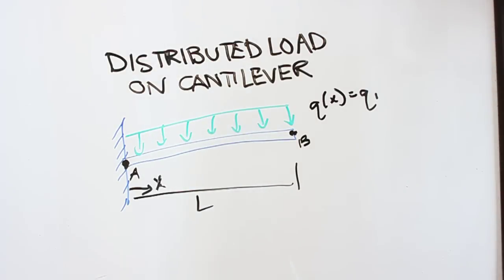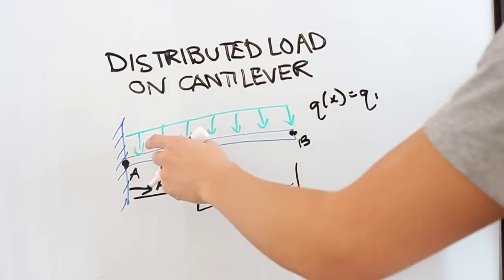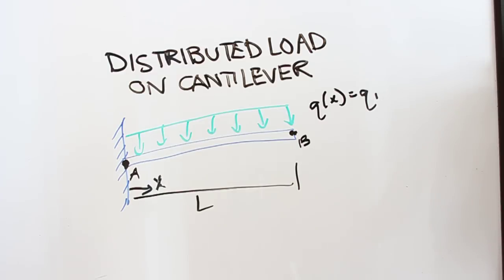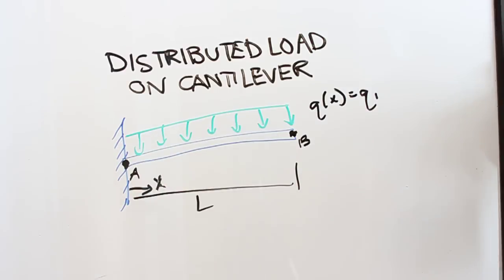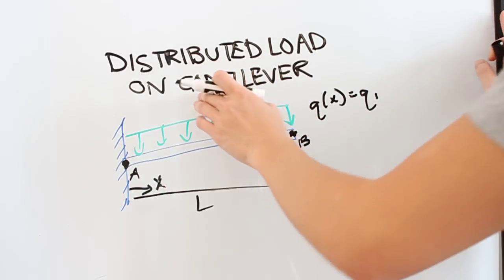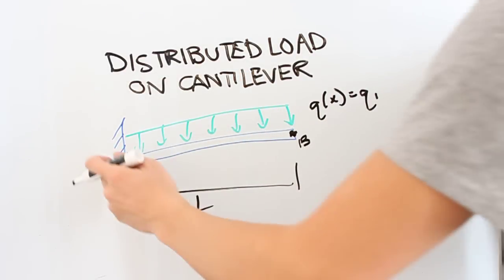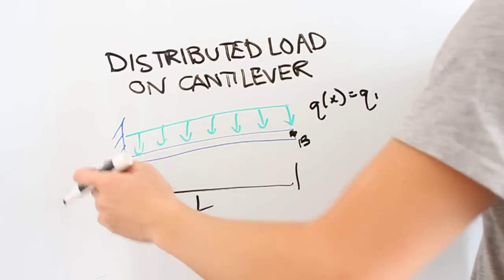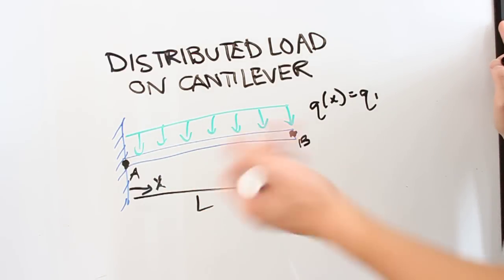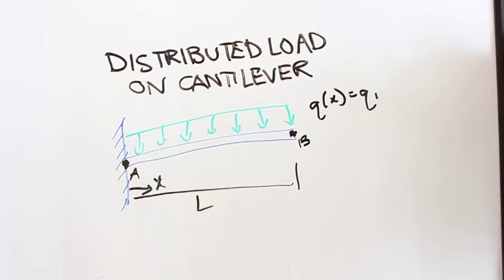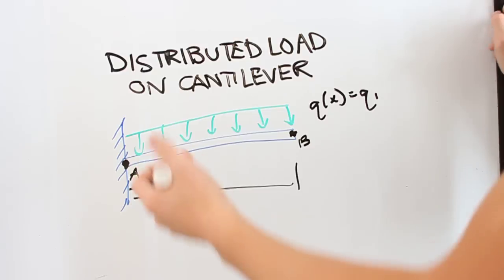So immediately, the first step always, after seeing this, understanding the problem, is to write out all the forces that haven't been shown. Because they've given you this, but they're not going to write down every force you could possibly have. And as we know, there won't be any here, but there'll be a lot at A. So going off what we know about fixed connections, those can give reaction forces of vertical force, horizontal forces, and moments. So we need to write down all three of those. So we can test all three to see if there are any of each in this problem.